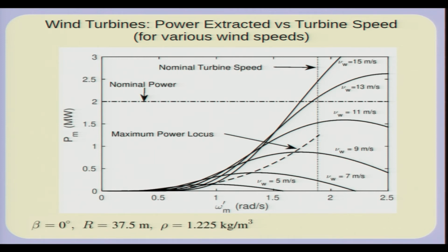So, for example, if the wind speed becomes very high and you keep the rotation speed of the turbine and the generator, which are rotating together through the gear, once you exceed this rated power, you can't operate it at more than the rated power. So, in such a case you will have to spill some of the power, you have to just let it go. So, you have to reduce the power output of the turbine, and that can be done by changing the pitch of the turbine blades. So, that is the typical control scheme which is employed for operating a wind turbine.